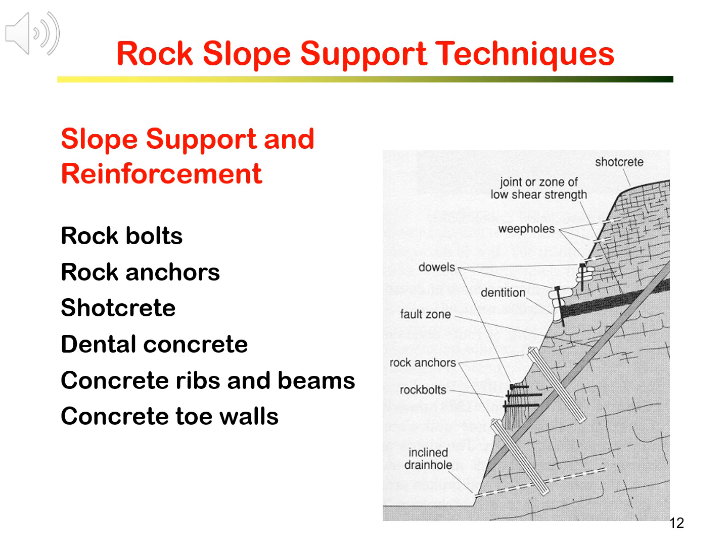The diagram here shows some of the main rock support and reinforcement techniques adopted in rock slope engineering. As we mentioned again and again, steel bolts, dowels, and anchors are widely used in rock stabilization to pin down rock blocks and the wedges formed by rock joints. Rock bolts are usually a few meters long, often end anchored to give immediate action to the rock mass. Rock anchors are longer and also thicker, with steel bars to intersect major geological discontinuities such as faults and bedding planes. They are used for anchoring large sliding planes.